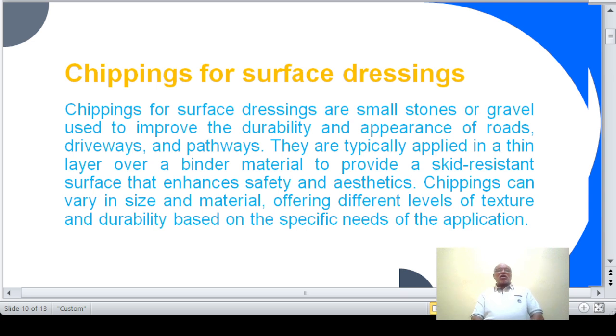Most aggregates have a special attraction for water rather than for bitumen. Hence, if heavy rain occurs within the first few hours, when adhesion has not fully developed, loss of chippings under the action of traffic is possible. Where wet weather damage is considered to be a severe risk, or the immersion test shows that the chippings have poor affinity with bitumen, an adhesion agent should be used.